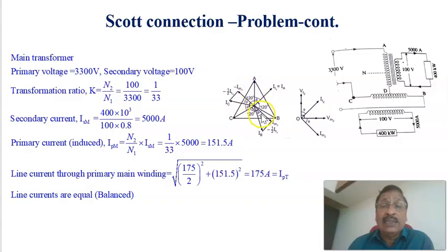This phasor diagram shows how the current is being added: to the current in the main winding due to this load, we add half of the teaser current. That vectorial sum is the total line current in phases B and C. We can see that when all the line currents are balanced, they are of equal magnitude and 120 degrees apart.